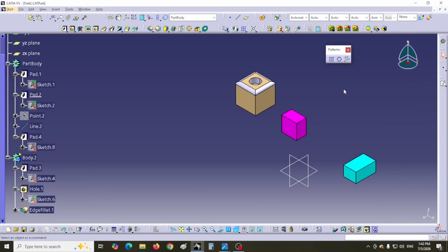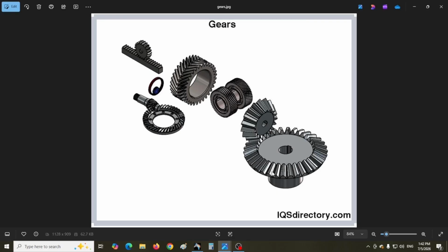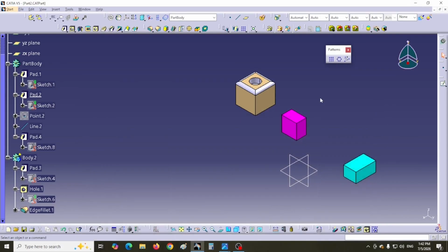During design, drawing each of these features one by one takes a lot of time and effort, so we first create one of the repeated features, then we copy the created feature based on a suitable pattern. CATIA uses three different methods for this job.